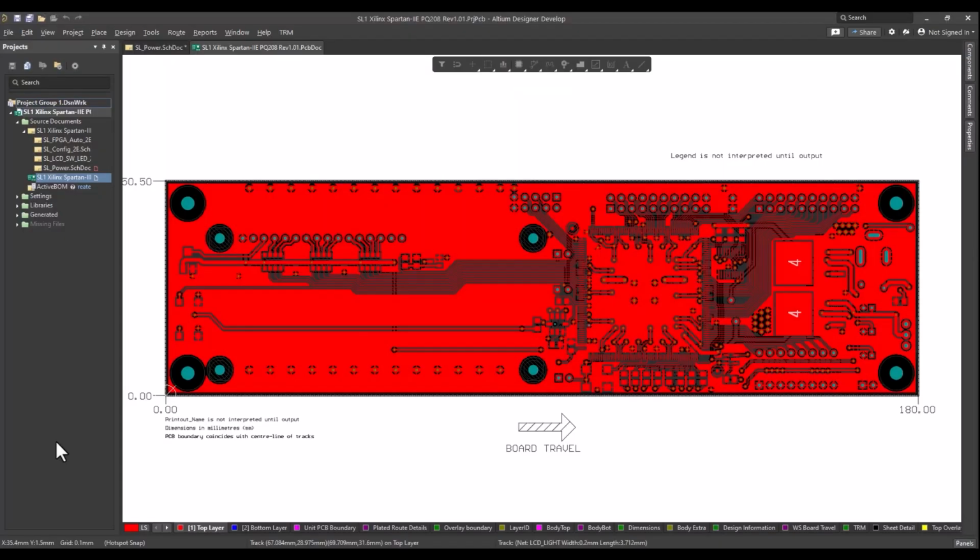This is the 2D view seen from top layer. Our intention is to bring current from this point somewhere here using the 5-volt net. There are several methods to assign amps to pins and pads. Option 1 is to use the schematics.